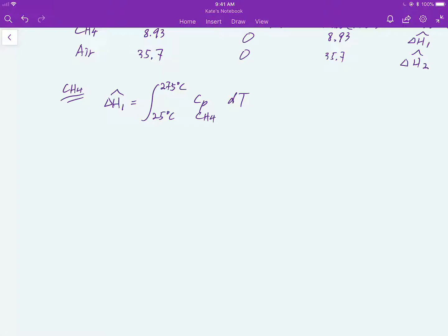Then there are two ways to write the equation for specific enthalpy change. That is the integral of the heat capacity. For heat capacity, there are two functions. I prefer the second way in the textbook in table B2 because of less calculation.